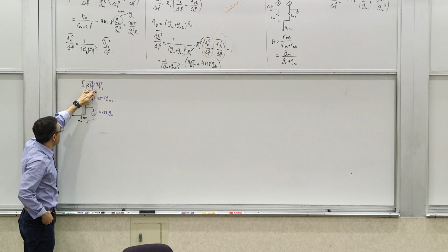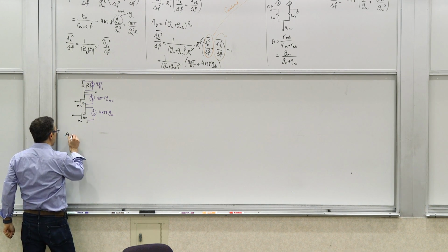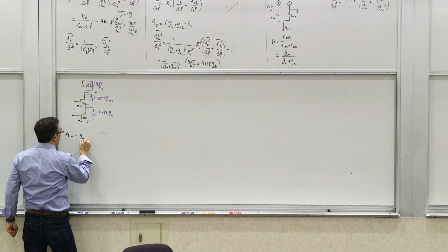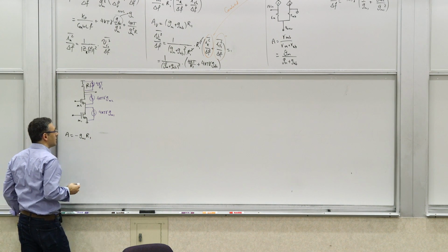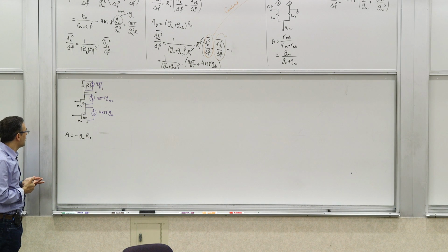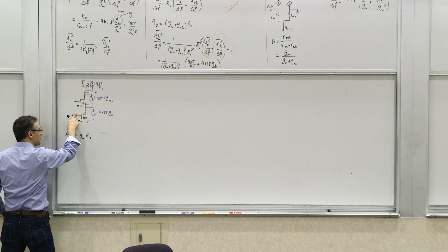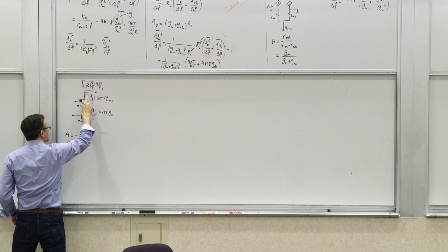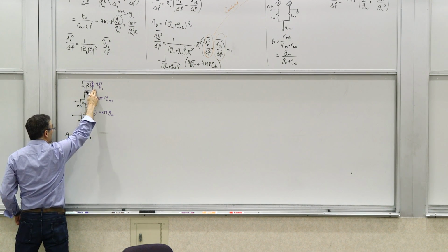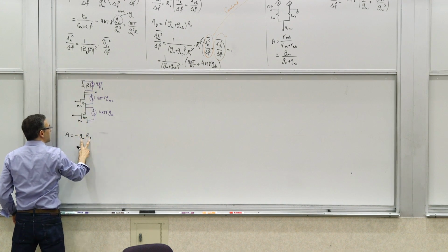Now, the transfer function from the output voltage to the input is a known thing. It's a gain, which is negative GM1 R1, the low frequency gain. So whatever voltage I have here, I can put a voltage source here of that voltage divided by this magnitude, or that voltage power divided by this magnitude squared.